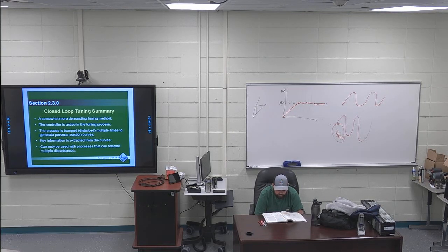The rest of that paragraph and the first two sentences of the next paragraph are a separate highlight. Figure 13 shows the response of a control system that is at the ultimate gain or proportional band. As shown, the controlled variable is oscillating at a constant amplitude and frequency. This is the critical frequency.